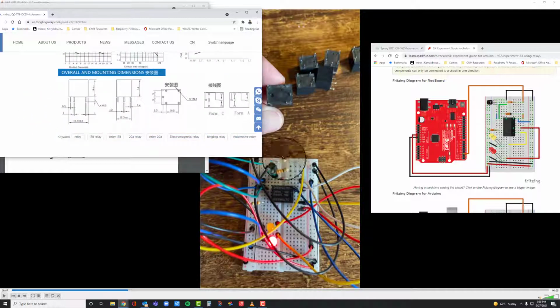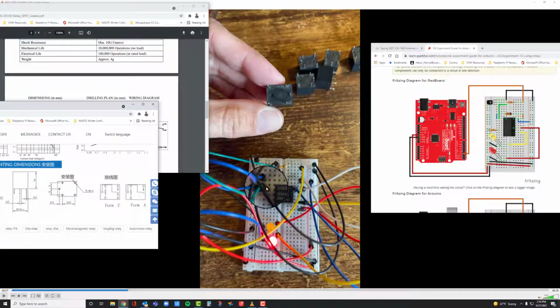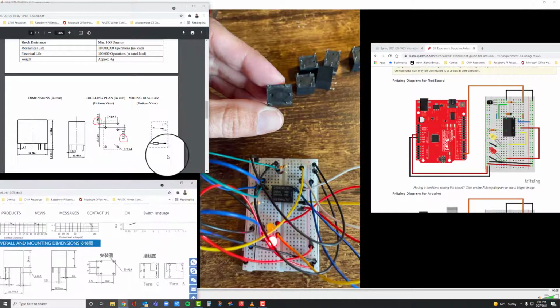Like if you have a relay that's not the same relay, I would try to find the mapping of the pins, find the mapping of the current, like your normal setup, the one that we're supposed to be using, and then map each of these to the right place, and then plug the appropriate wires into the correct location. So I'm hoping that that helps. I know it may seem confusing, but in the end, this is a simple relay, right, and it's got the same pass-through components that the other relay that we're using has.